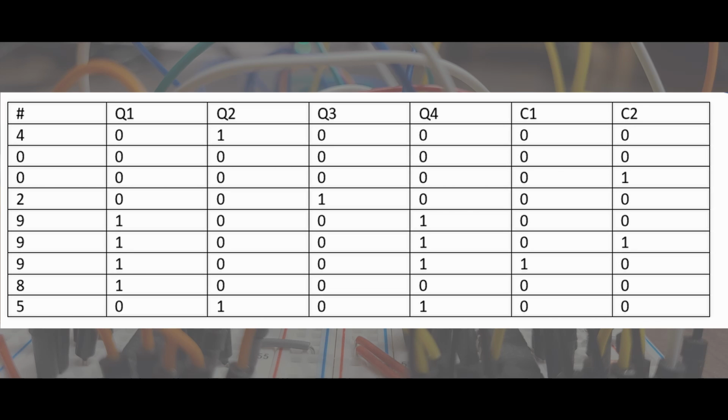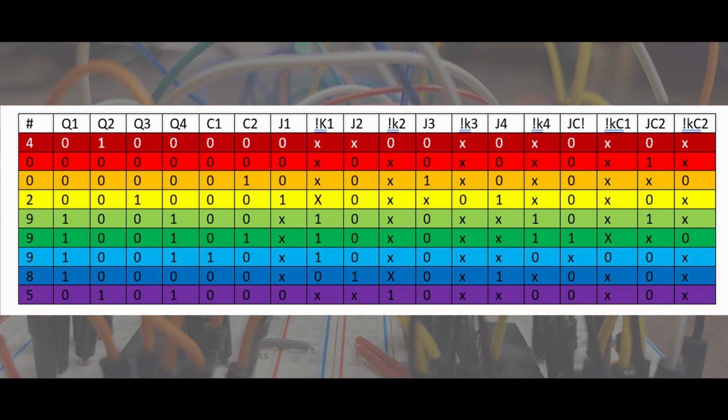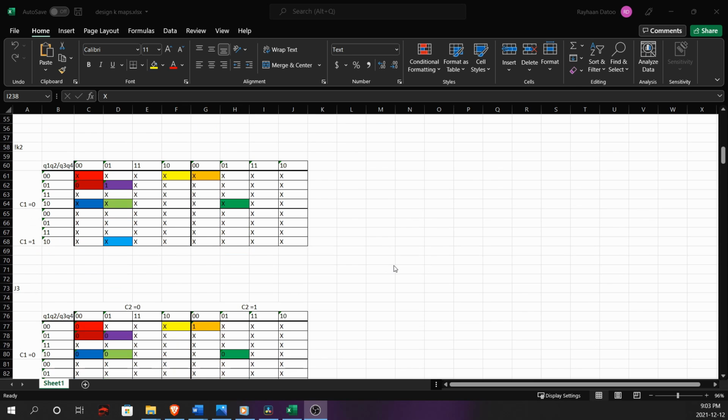The goal is to minimize the amount of logic gates needed, and so by setting most of the conditions to low, I am limiting the possibility for a flip-flop to output a high 2 times in a row. If a flip-flop never goes from a high to a high, then at least one of its inputs will always be 0. Next, I generated my input table, and then started a K-mapping procedure to determine my logic equations.